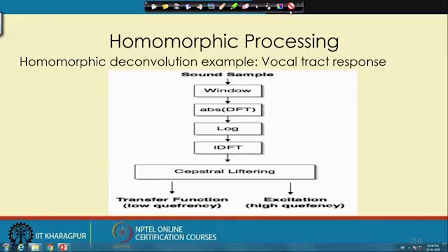If we take a small window, within that there is no change. So we select such a window of time and limit the signal within the window, so that the assumption of stationarity is maintained. So the first job is to limit the signal within the window.